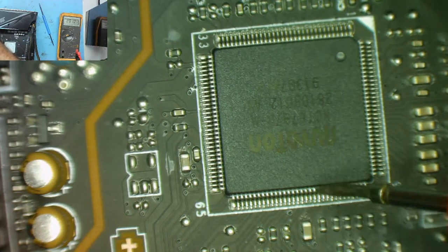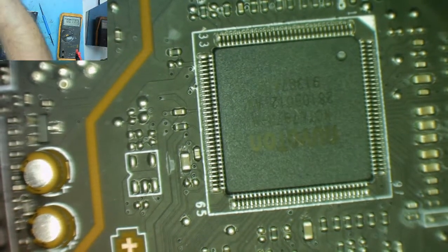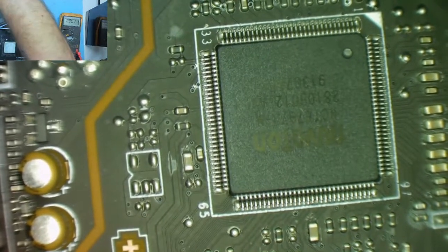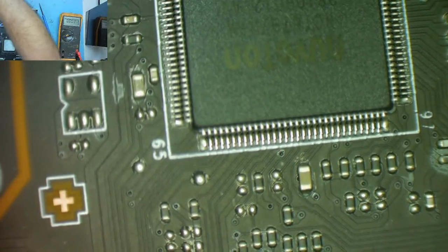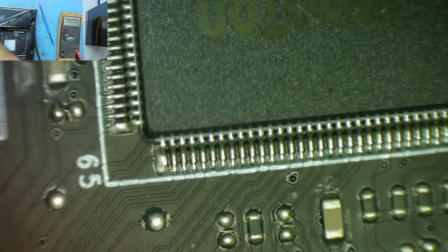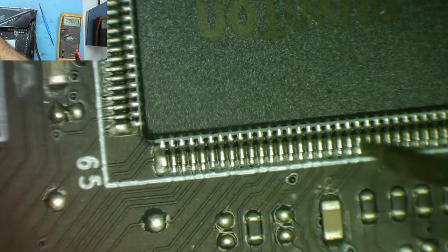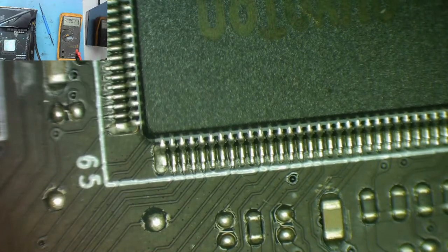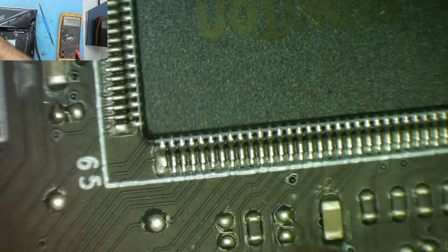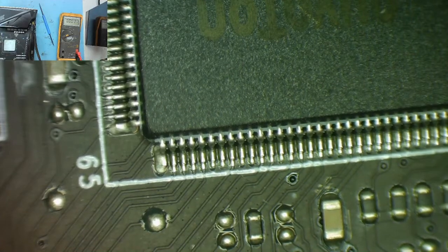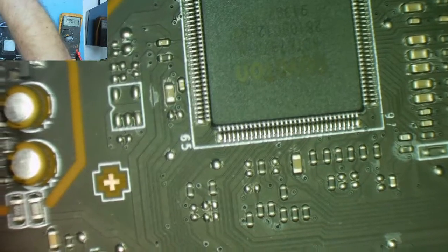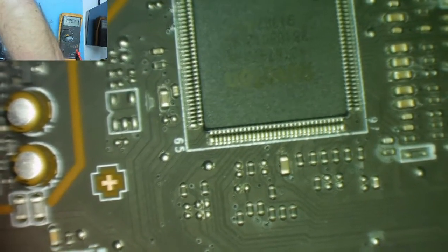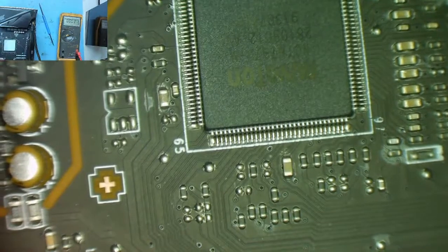And we can very confidently say, we might even be able to see where it goes, just by zooming in on the microscope, that it goes to the SIO, but we know it will do. It does, don't it? You can see it. Let's just get some zoom on there. Yeah, there you go. You can see the 3.3 goes here. Can you see that track from the end of there to there? So we know 100% we got 3.3 on that. I was pretty confident we would have because we had 3.3 on the on-off switch, and that's where it comes from. Okay, so that's there.